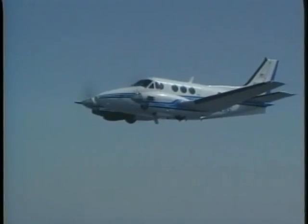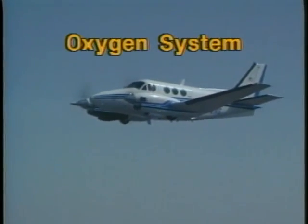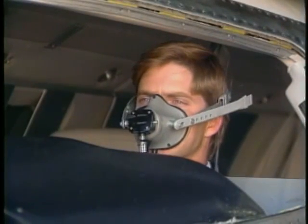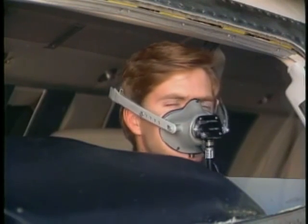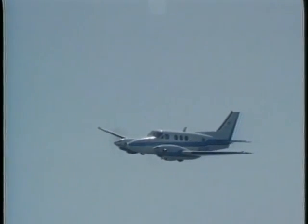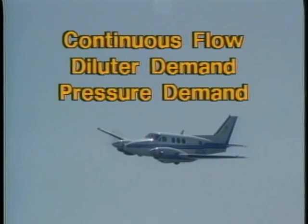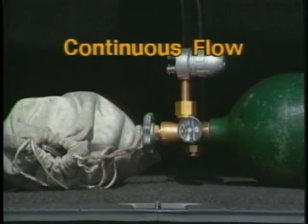Another environmental control system commonly found on high-performance aircraft is an oxygen system. Federal aviation regulations require the use of supplemental oxygen above certain altitudes in order to compensate for the body's inability to get enough oxygen through normal respiration. There are three types of oxygen systems: continuous flow, diluter demand, and pressure demand. The first one we'll look at is the continuous flow system.